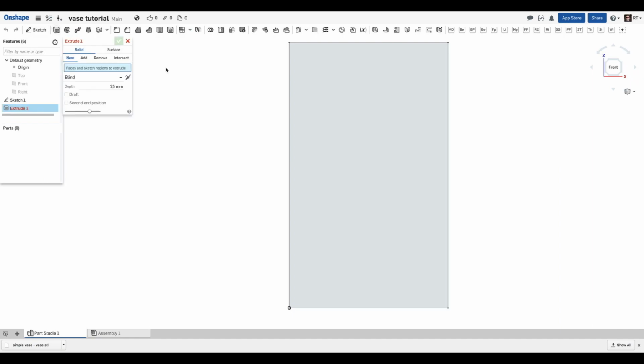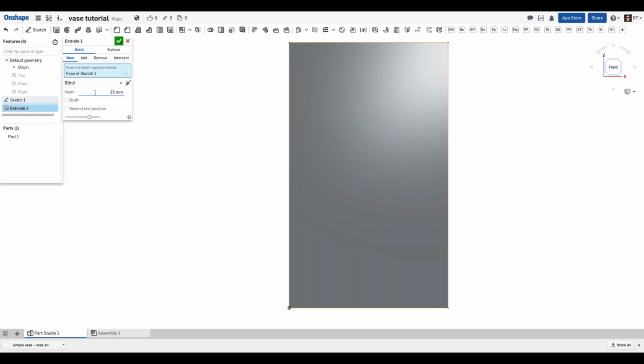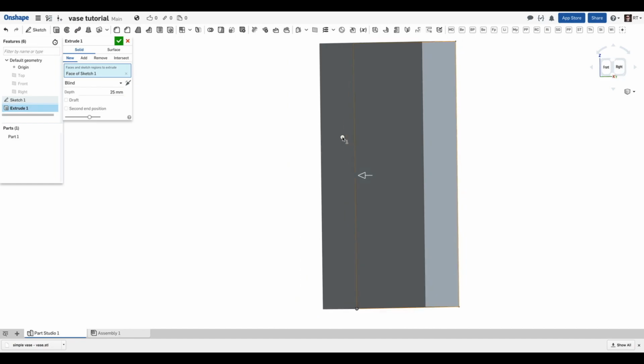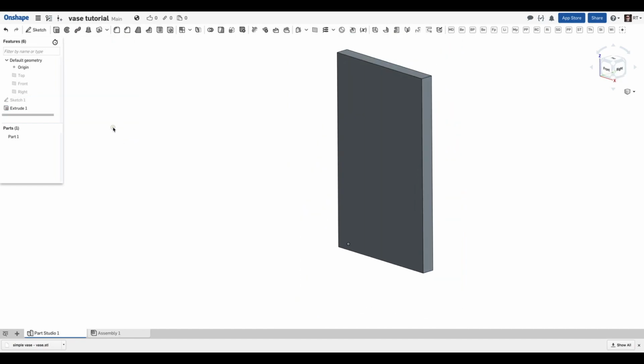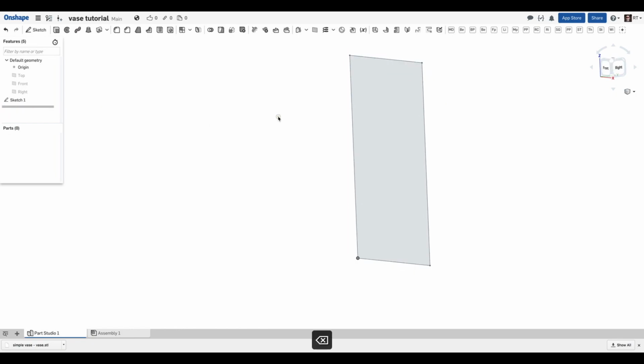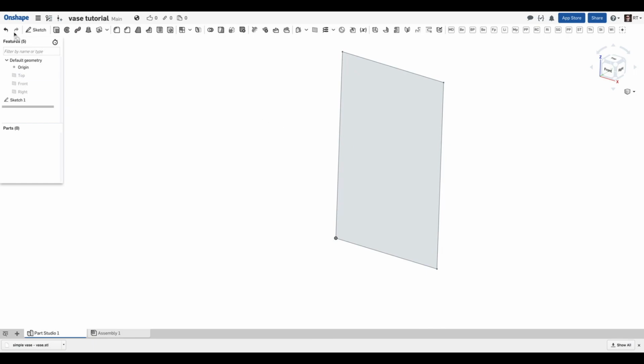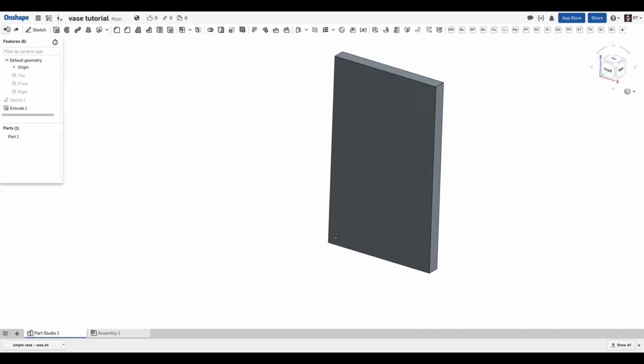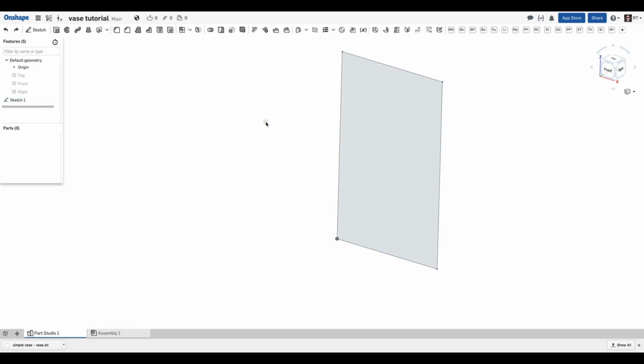This first tool will extrude whatever face or sketch that you design, showing a light gray area, so then we can extrude that. So we'll select that, and it automatically does a depth of 25 millimeters. Since we're viewing normal to that plane, we need to right click and rotate. Now I just created an object. We can select this here, hit the delete key. One way to get rid of that, we can also undo. Undo will bring it back. Has unlimited levels of undo. Undo again. Similar results.